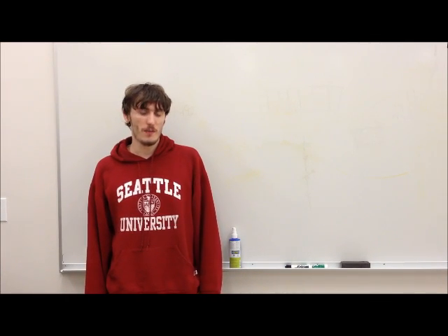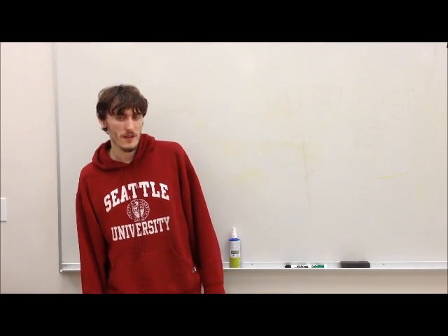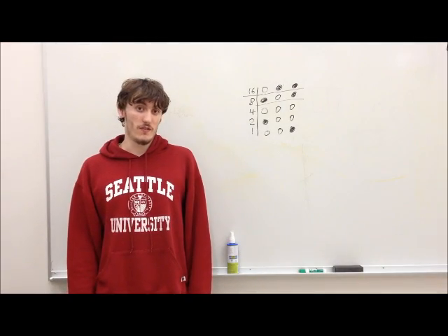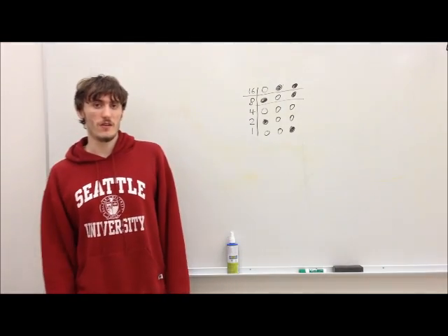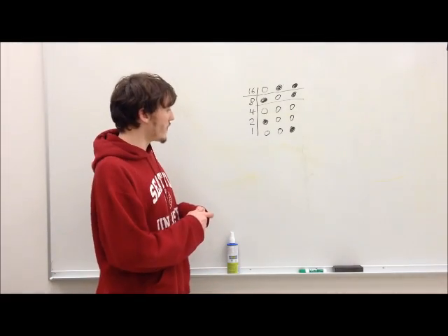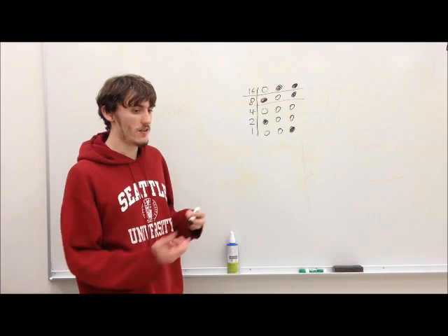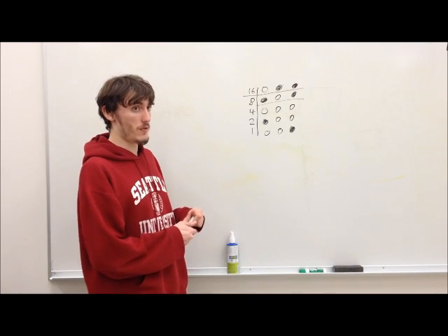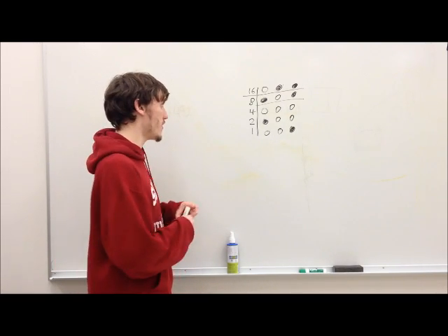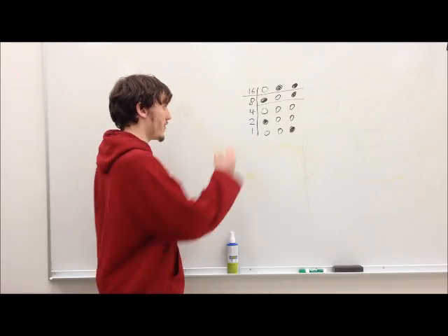Unfortunately, this can require polling very quickly. To avoid having to poll at high frequencies, we're using a hardware counter. Now, we don't want to use a very wide bus between the counter and our device, so we tried to come up with a counting method that would be able to use a hardware counter which still had maybe only a 4-bit bus or so.